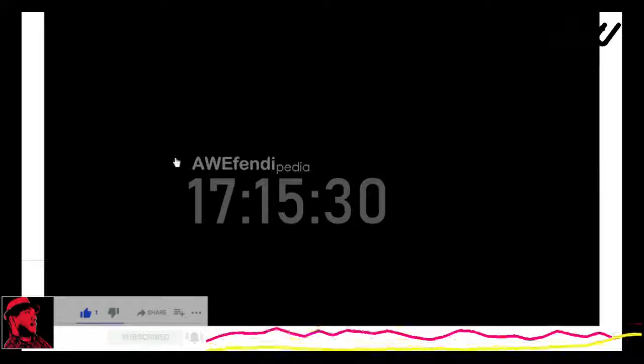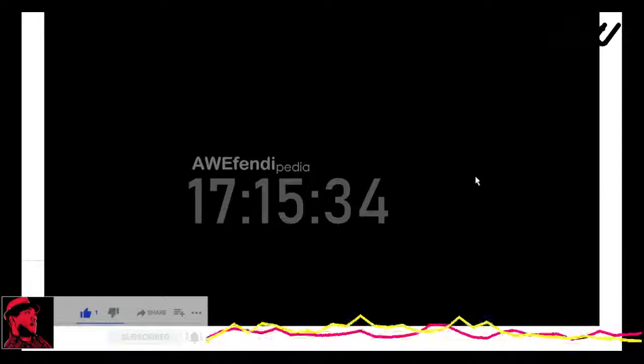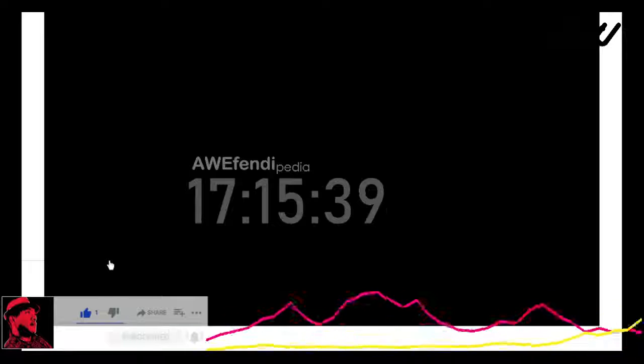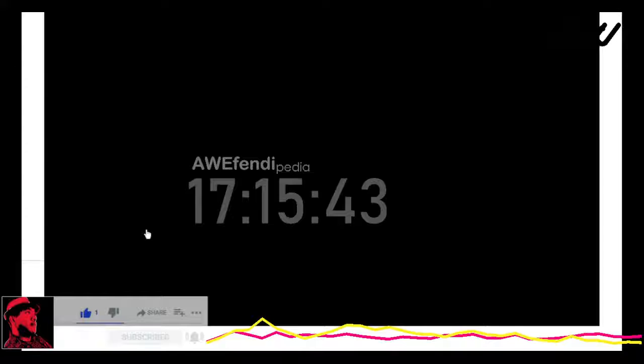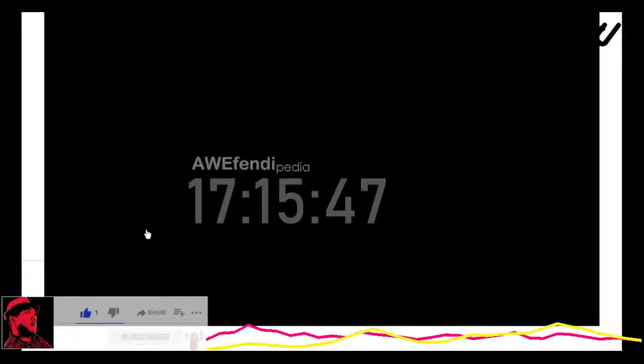We brought that in. Kevin went through the terrain modeling aspect, correcting rod heights, joining break lines, and so forth to get the topo where we wanted it to be. Now, how do we bring that data in so that we can use it to create horizontal geometry? Well, since everything lives in the DGN, we're going to use reference files.